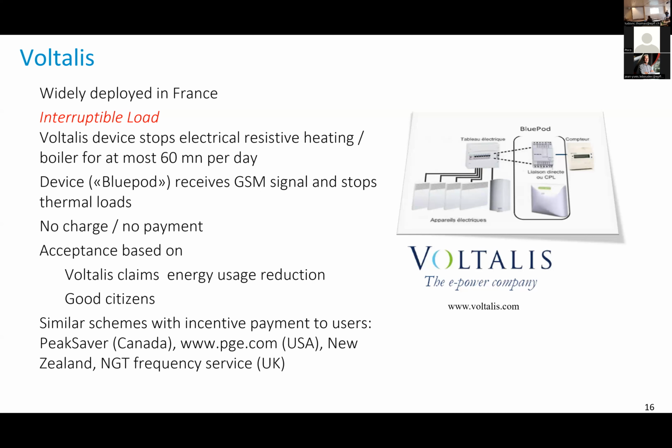When RTE is saying, for example, oh, I need 1 gigawatt of power in 2 hours from now, then Voltalis raises their hand and says, we can do it. In 2 hours, we will send a signal to 10 million devices that will switch off, that will reduce the consumption by 1 gigawatt, according to our estimations. And for RTE, it is the same as having 1 gigawatt of extra power being generated.